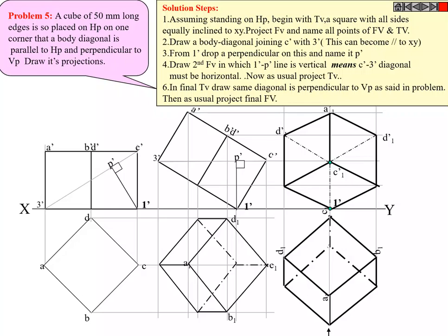Extend the projection lines to the front view where the horizontal and vertical lines coincide. Locate the points and draw the required front view of the cube. Like this you'll be able to get the required front view. So when you read the data, you have to be able to satisfy the conditions, otherwise you have to check the points whether they satisfy or not. You have to draw as per the problem data which is defined there.